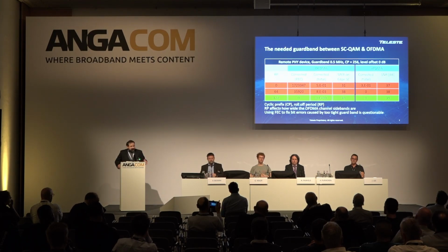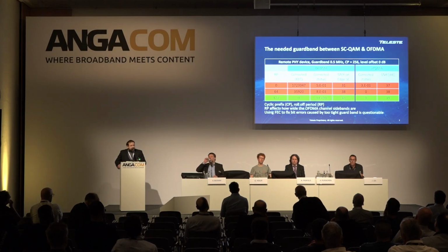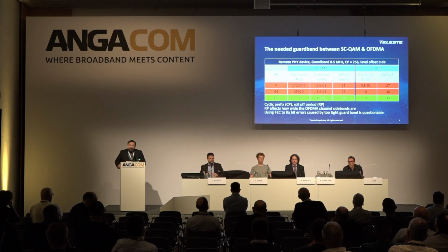You don't have corrected bits, or FEC doesn't show that it has to correct any bits. MER is excellent. MER is also excellent with the ATDMA channel, so with the single carrier QAM channel, that is the highest single carrier QAM channel that you have in your network.